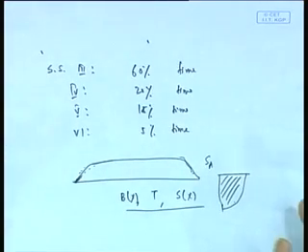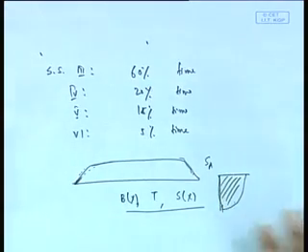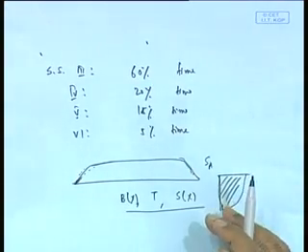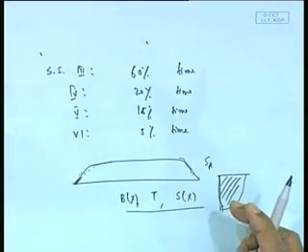And then there are programs like strip theory programs available by which you can estimate RAOs. And once you have RAO, of course, you can always go to the algebraic process of determining response in irregular waves. Okay. So therefore, at the design stage, I have done a design in one of the loops, and at that particular loop point, when I have frozen this, I can easily do the seakeeping calculation and find out the entire criteria. So you know what I am saying, therefore, is that it can be easily done.